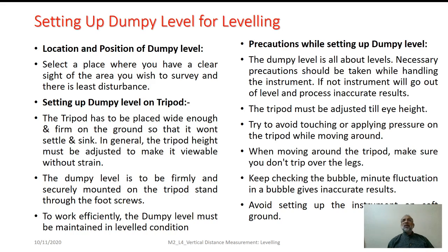We have to take certain precautions while setting the dumpy level. Here one must see that the position of the bubble remains at the center for the entire time that we take to carry out the leveling work.